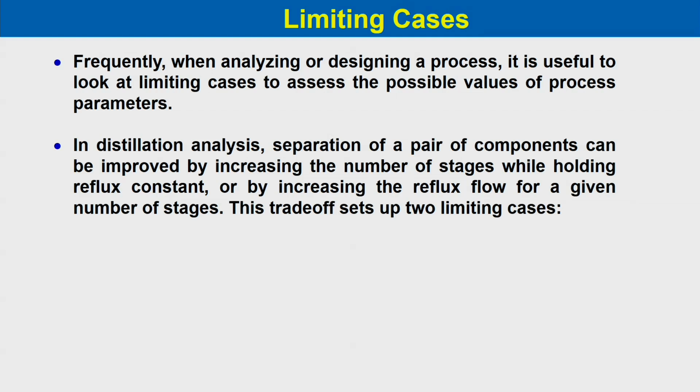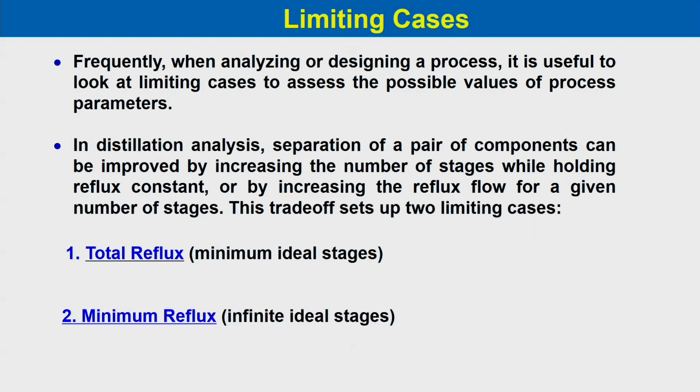In distillation analysis, separation of a pair of components can be improved by increasing the number of stages while holding the reflux constant, or by increasing the reflux flow for a given number of stages. This trade-off sets up two limiting cases. One is total reflux, that is minimum number of stages, and another one is minimum reflux, infinite number of stages.